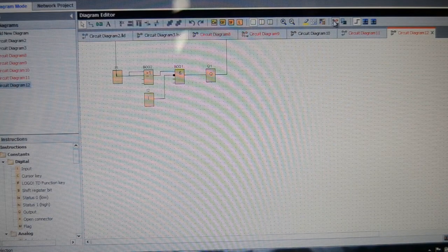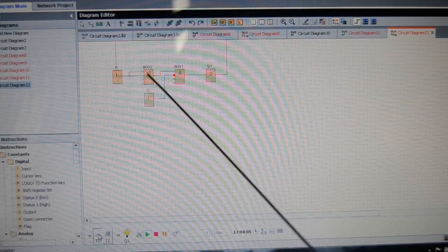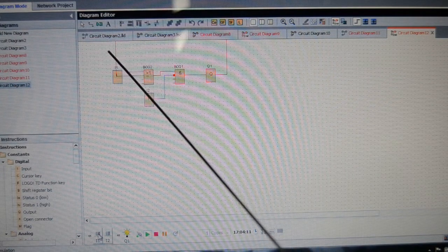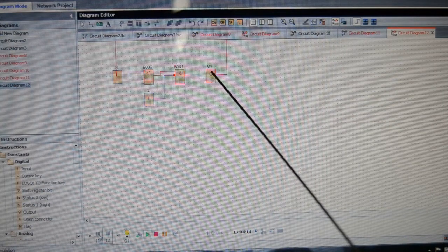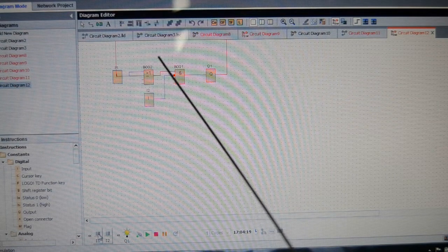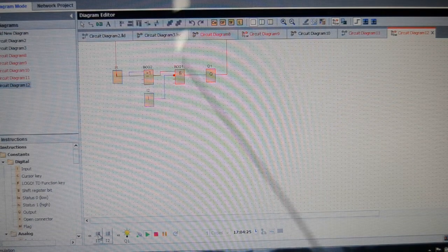We can see if we load up the simulation, we have exactly the same thing happening. So if I press the momentary switch here, you can see, in fact if I hold it down, you can see the lines of logic flowing. So we have from the input, the logic is going to the OR gate here, which if I release, it stops coming from here, but it's flowing down this line and along here from Q. So that's giving us our locked in loop, and because it's an OR gate, it will accept either input and still become true and send the logic on to the next gate.